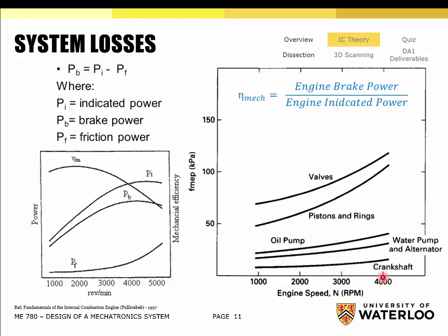Okay? If you have a water-cooled engine, and an engine that you want to start with a key for your car, let's say with a battery operated ignition, that you can just crank the engine over and it'll start itself, you need two things. You need to be able to charge the battery, and you need to be able to circulate the water through the engine. Generally those are driven via a belt on the front of the engine, and that's what's going to turn this generation device, which they call an alternator, and that's going to charge the battery. And then the water pump is a vane style pump generally that's just going to circulate coolant throughout the engine. So that contributes to another small portion here.